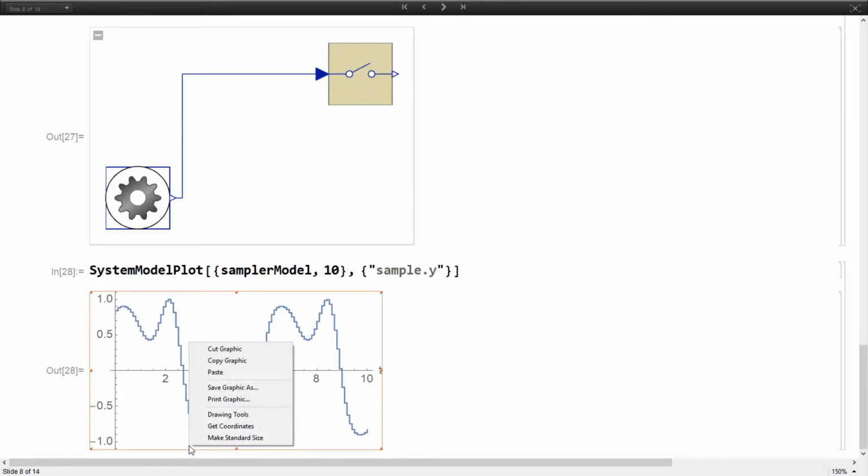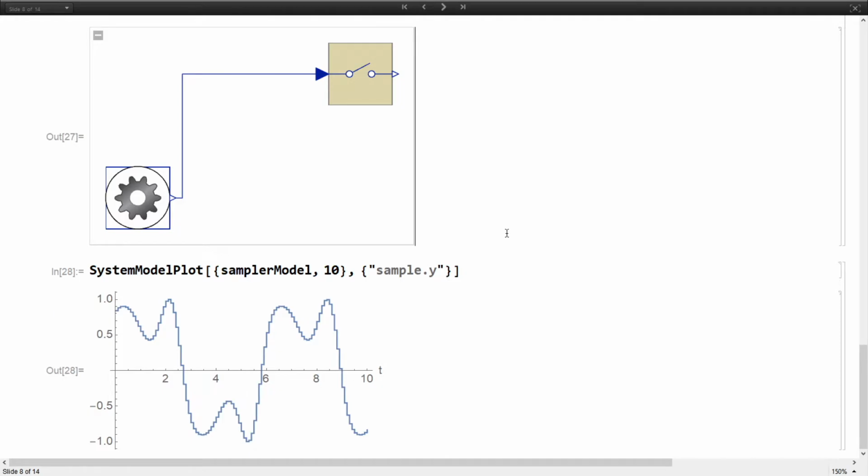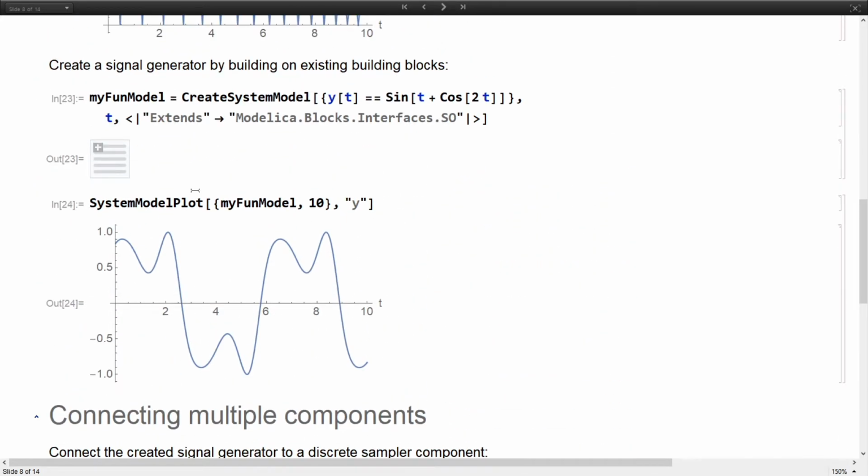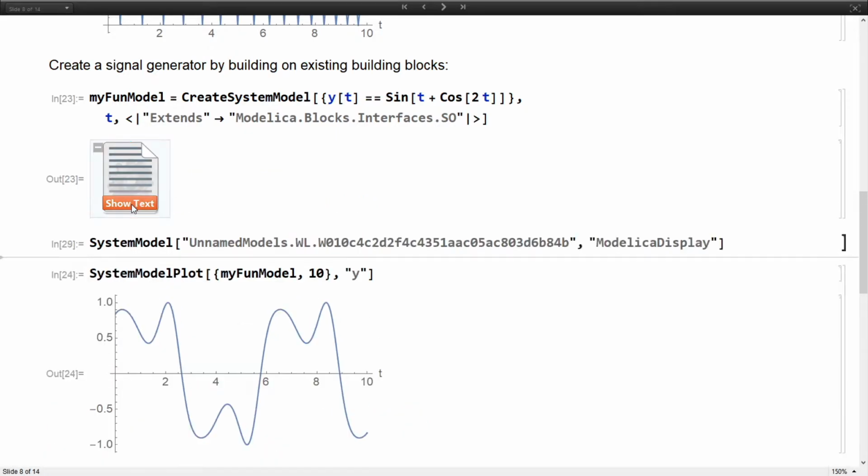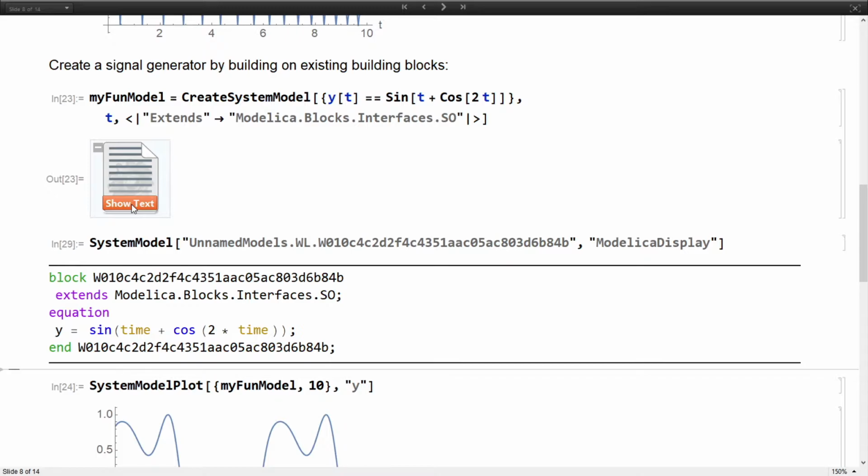So this will transform the differential equation you had in Mathematica to Modelica? Yes, it will transform it to Modelica code, so I can briefly show it. I think if I open up this one. So at that point, you don't really need Mathematica to run the model itself? No, but it's very useful if you want to do, for example, programmatic model creation. You want to try many different designs for your model, and then you could create a table which just spits out different system models, and then you plug it into wherever you want it to control, and you can evaluate which one works the best.